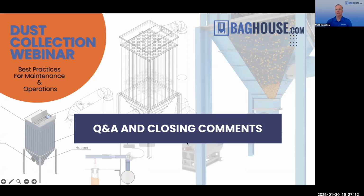Occasionally there's some other dimensions we need. The best possible scenario is if you have an extra bag, you can just send it to us. That way we can get it to the filter shop and let them match the snap band diameter, the flat width, all those things. If you send your bag over here to Scott, he can take those measurements for you and we can confirm it will fit, because some of those measurements are easier to take than others. Did I answer the question?